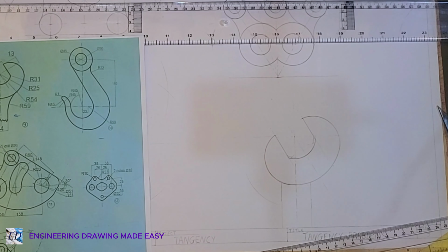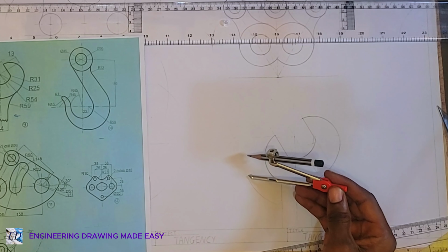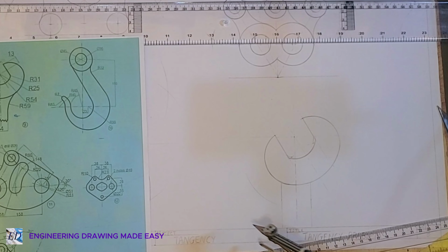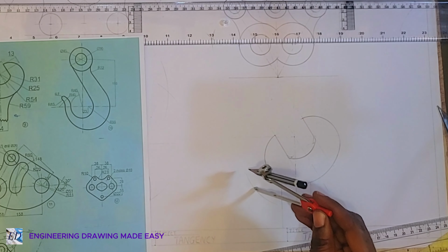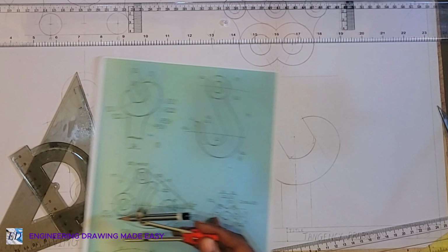That is the right way to go. That is the genuine thing to do. But if you are not sure where the center is, or you don't have much time, right, one thing you can do is that the center that would make it tangent to both arcs is on this line somewhere, this arc that we've drawn, right? So wherever the center is should definitely be on this line,